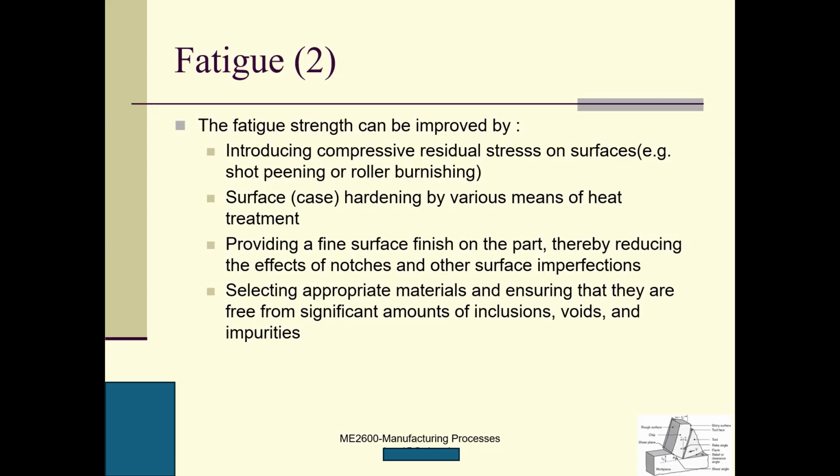After some time, carbon atoms from around the chamber will come to your workpiece. As a result, two things we can accomplish. First, the hardness of the workpiece is enhanced. Second, compressive residual stress will be induced on the surface by the carbon atoms.